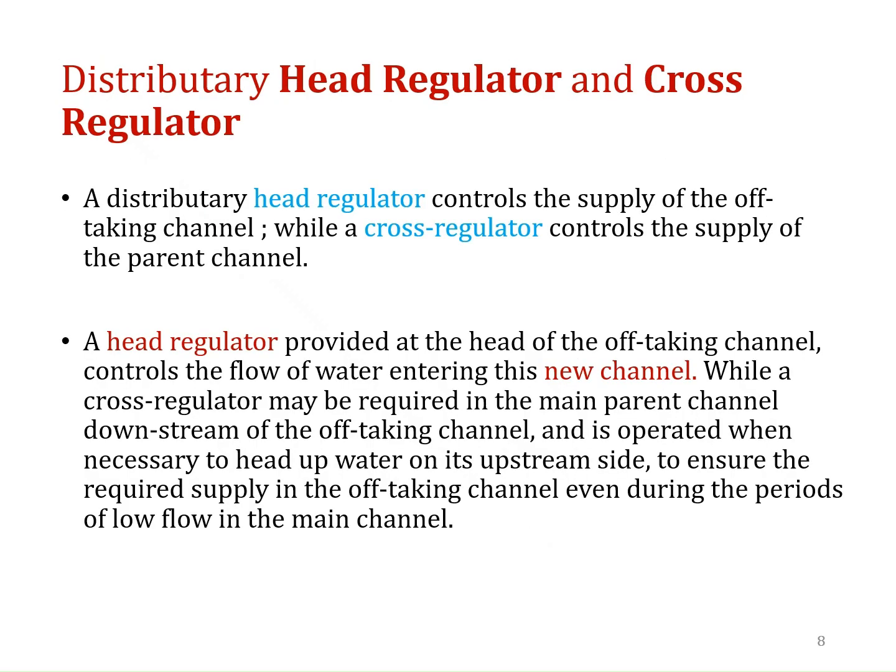Okay, let's talk about distributary head regulators and cross regulators. A distributary head regulator controls the supply of the off-taking channel, while the cross regulator controls the supply of the parent channel. As we discussed before, the cross regulator is on the parent channel, and the head regulator is on the off-taking channel. The head regulator, provided at the head of the off-taking channel, controls the flow of water entering the new channel. So you have gates in the head regulator as well as in the cross regulator.